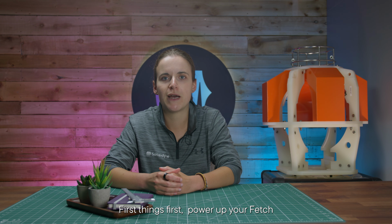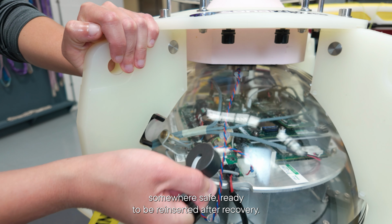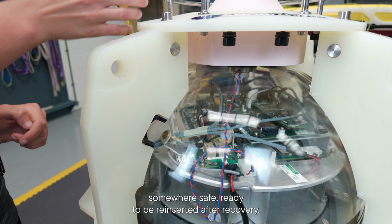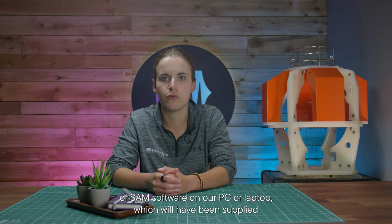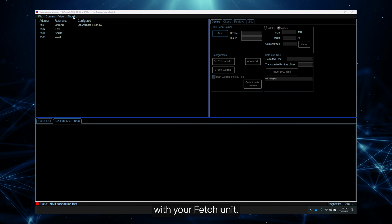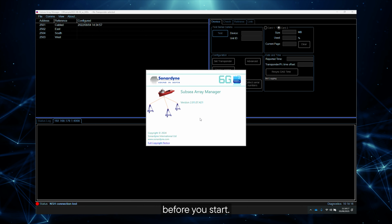First things first, power up your fetch by removing the battery disconnect plug from its holder and store this somewhere safe, ready to be reinserted after recovery. Once your fetch is powered up, we need to open the Subsea Array Manager, or SAM, software on our PC or laptop, which will have been supplied with your fetch unit. Make sure that you're running the most up-to-date version of the software before you start.